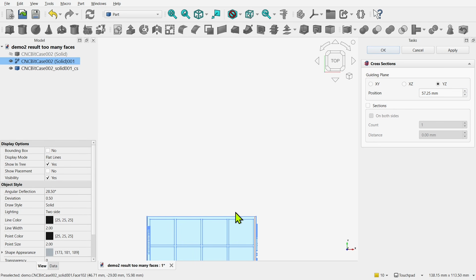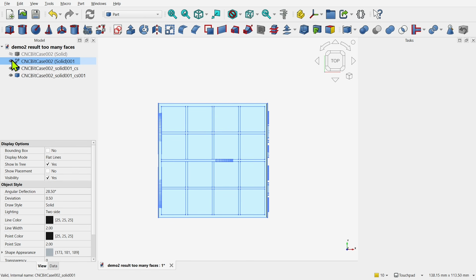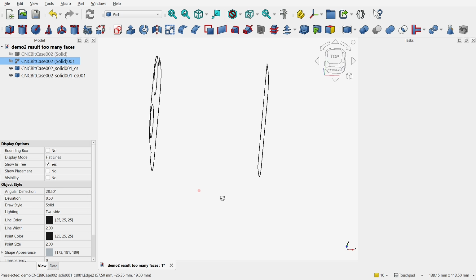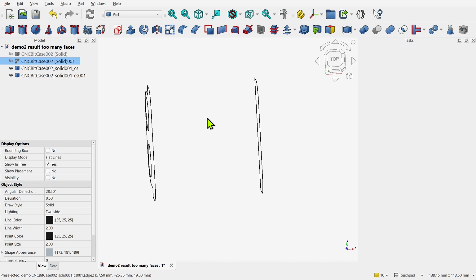Look from the top, check the intersection, so 5.8, and we'll back it back a bit to 7.5 and hit OK. So we have the back and the front, and we could create a stack of cross sections as well. This is very good for revolves if we have a circular object and we want to create a cross section through the middle to find our revolve profile.